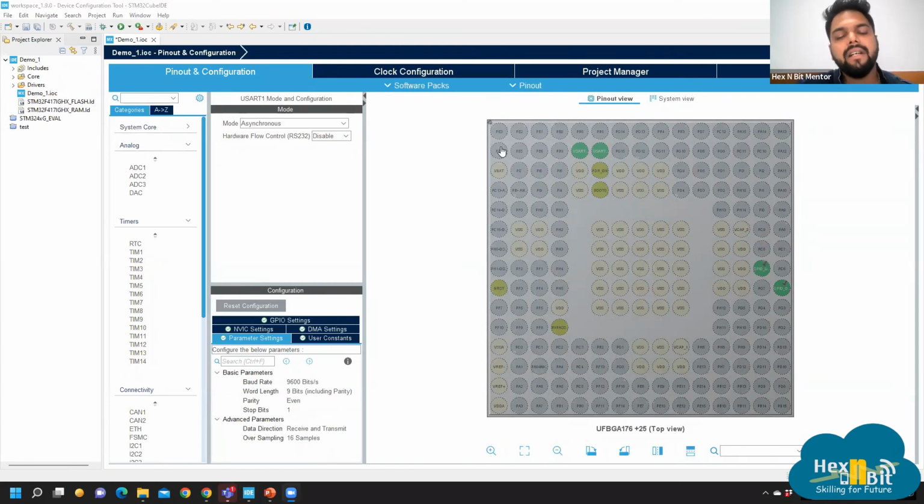So Shams, it depends on the application that you're using. On the parity bit, the benefit of using odd and even parity: this redundancy check is totally dependent on the application you're working on. If it supports even and odd parity bits, then you have to set it up. Otherwise, you can keep it as none. It totally depends on the sensor or any application that you're using. Accordingly, you have to select odd, even, or none. It is totally application dependent.